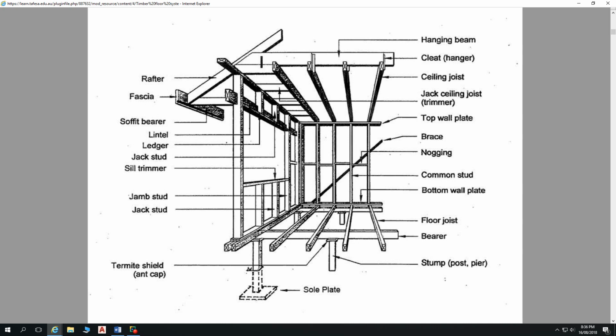There are options around there. So there are various different products like thick sheet. You can get various thicknesses of thick sheet, so 19 millimetres and 15 millimetres. They require different joist spacings.